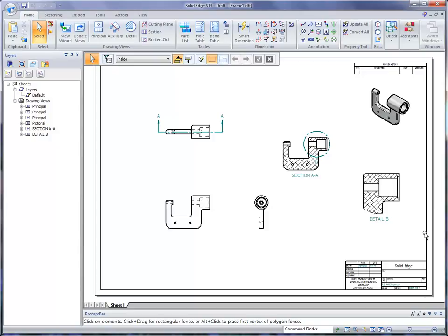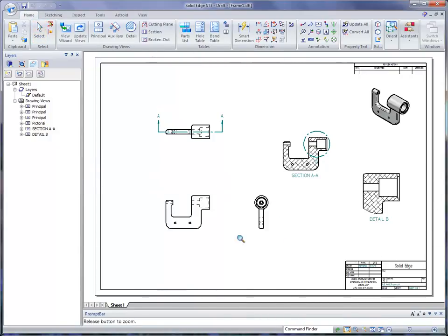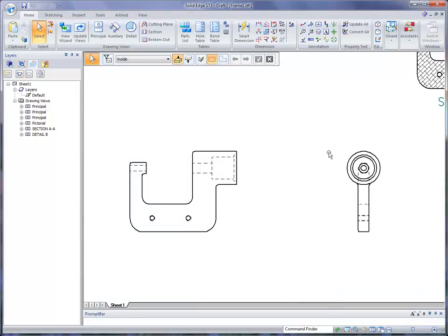The first thing that we want to do is take a look at some dimensioning. So what I'm going to do is just area up on our view here. And if you have created views in your 3D model, no point in not using them, so we're going to go ahead and grab the retrieve dimensions command, and then we'll go to the pull down menu, and of course you can change the standard in which you want to work. In this case we're using the ANSI millimeter.